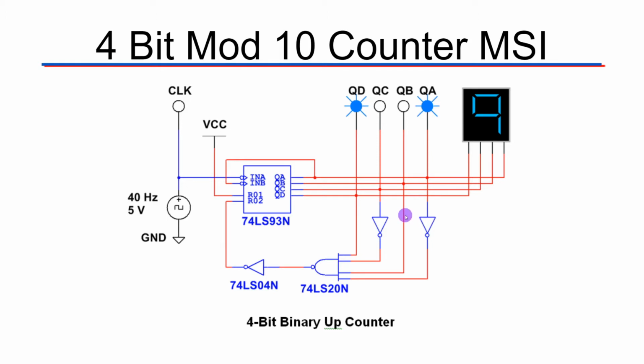And then the third piece overall, the logic implementation part, or the extension to why this is not just a regular 4-bit counter, is that we want a way to show a count that looks like a decimal ones place. The intended behavior of the circuit is that we want to see a range from 0 to 9 in sequence. And to do that, we know that we need a binary value that holds at least up to 9. So we can't do this with 3 bits, right?